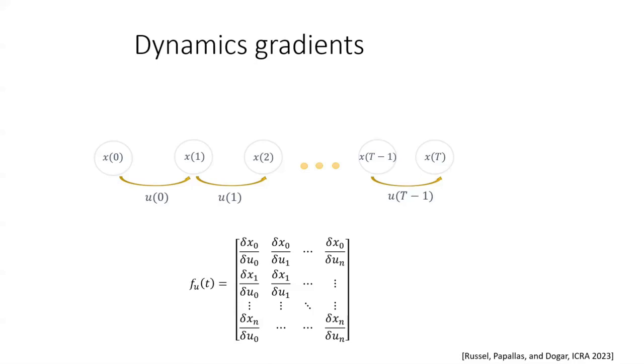So as you change a certain control a little, what does it say? Let's say this is how much torque we apply to a certain joint. So this says, okay, as the torque I apply to this joint changes a little, how does object one's X position change, right? So this is kind of saying that. But you need to basically compute these big matrices so that you can do gradient-based trajectory optimization. Okay, and you need to compute these. And when you need to compute these, if you have your dynamics and your cost and everything as analytical functions, you can actually take analytical gradients.